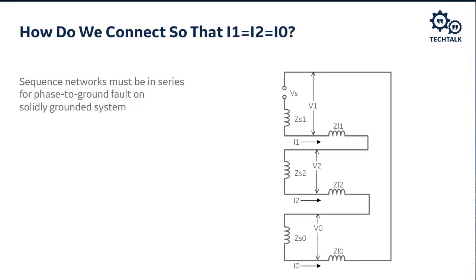And all we really need to know now is the system impedances and the line impedances, or the source impedances, I'm calling it there. Once we know those, we can calculate the positive sequence current, we can calculate those voltages, and then, using the equations we showed previously, we can turn those back into phase quantities. That's what we're going to do in a few slides when we calculate some fault currents.